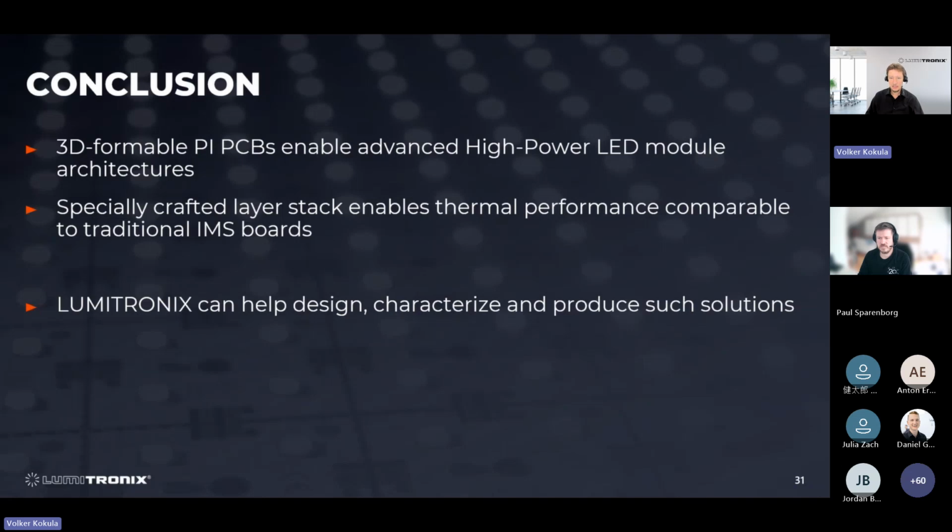Using aluminium housings or even aluminium PCBs is more done for high-power applications. So the plastic housing there is more for mechanical stability and less for the heat management of a PCB, since for mid-power designs, most of the heat is actually radiated away and not conducted away.